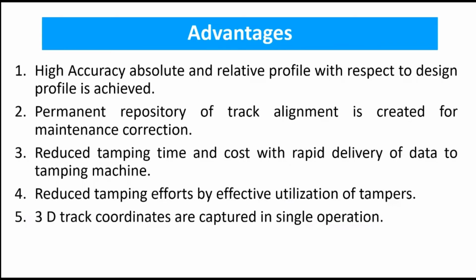Excuse me, sir. While the trolley is online, when we have any cross level difference, how could it match, sir? Will there be any differences, sir? Whatever the cross level difference is there, that will also be picked up, because we are picking up the center line coordinates with respect to the control points which are established beside the track.